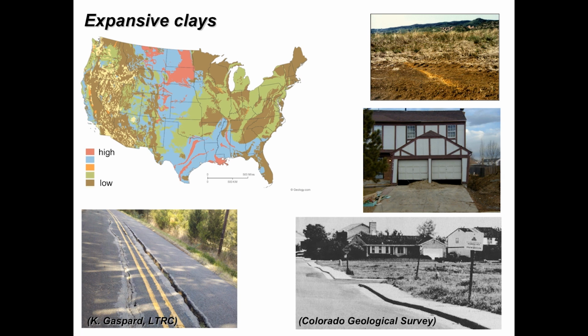The footprint of a house or certainly a road would span that area, and this leads to differential movements. If this system were to wet up, for example, the heave experienced by the structure overlying these multiple deposits, each with a different swelling potential, the heave would be very differential. Portions of the house, for example, would move a lot more than other portions of the house that are founded on less expansive material, and it's that differential movement that's really destructive to overlying structures.